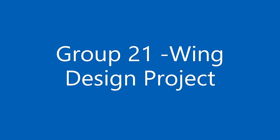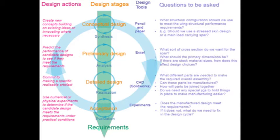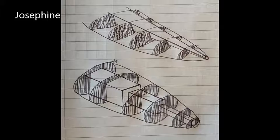The design process involves sketching, Excel, CAD modeling and simulating, and building and testing. First, we came up with some sketches to understand the internal structure of the wing. Then we sketched spar cross sections to test in Excel. We tested the spars that passed the test in Solidworks and repeated these tests in the lab to investigate further.